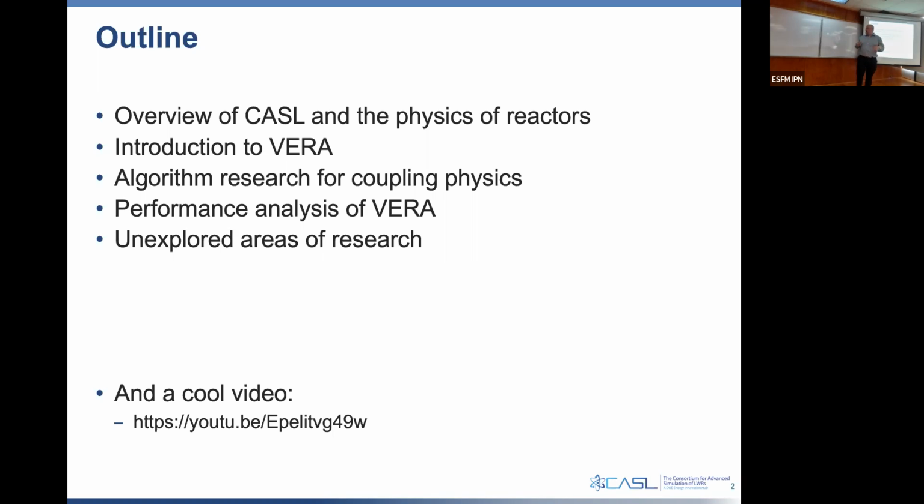In subchannel, when we went from an assembly averaged flow where we had a 20 centimeter size flow mesh cell to a single channel where we now had a centimeter size channel, that's a factor of 20 in X, a factor of 20 in Y. And if you're going to shrink it down in X and Y, you also want to shrink it in Z. So it's a factor of 20 smaller in Z. So just in the subchannel, to go from an assembly average flow to modeling every channel, you're going a factor of 20 cubed bigger in size. So you're going a factor of 8,000 bigger.